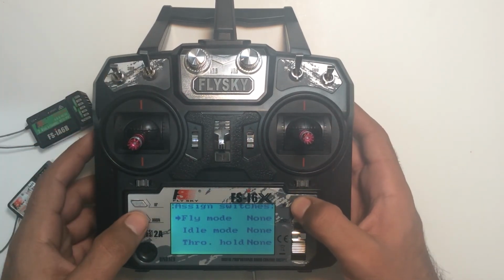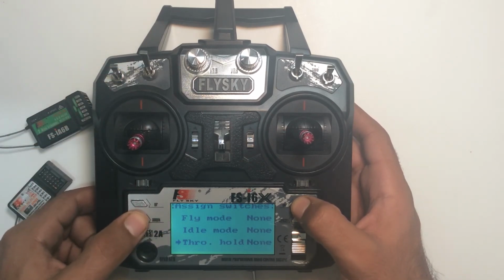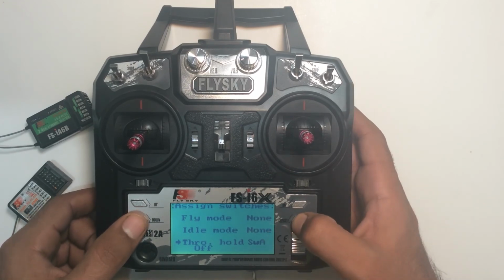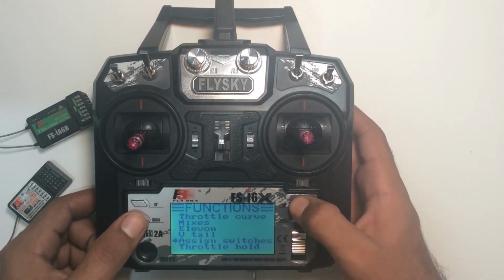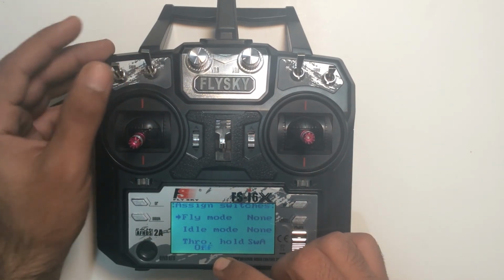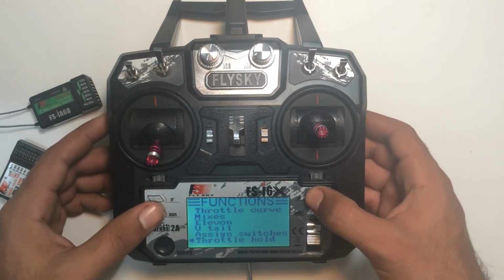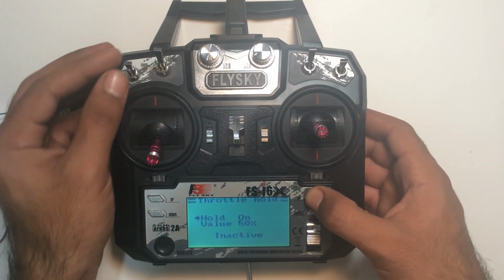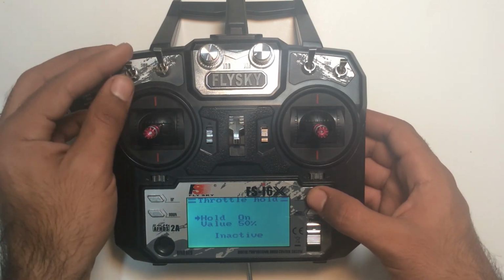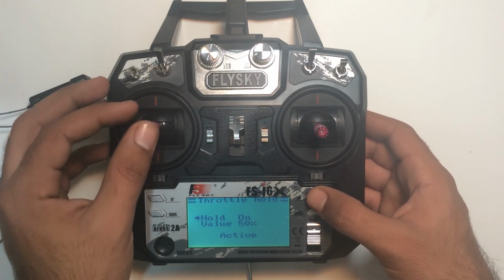For example, I want switch A to be functioning as a throttle hold switch, so I select switch A here and I press and hold cancel, and when I see here, upon switch A I turn on the throttle hold function. So the next one is the throttle hold, and in throttle hold we have control over our throttle, that if we activate it, our throttle will be at the specific position we want.